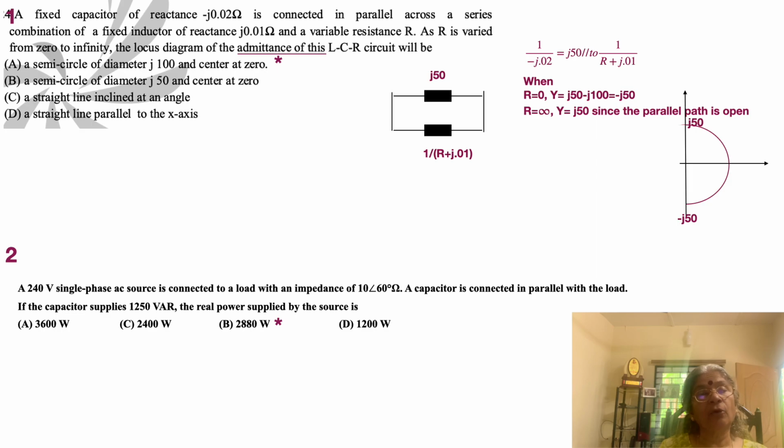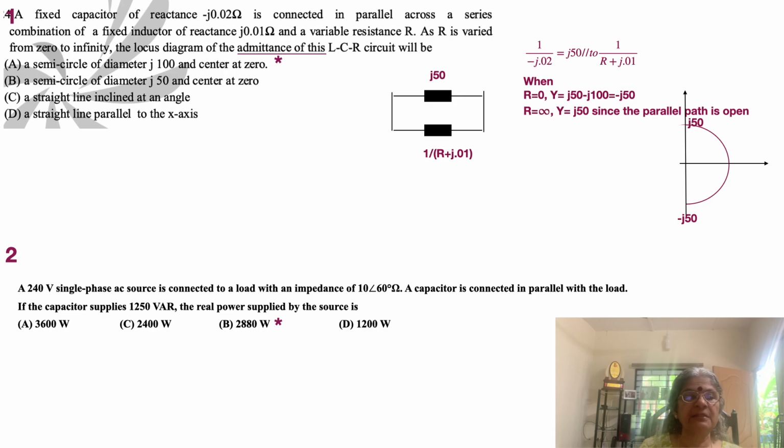But our requirement is only to find out the active power involved. So this is the distinction that we have to make. What's the active power involved? We have 240 volts. It is an RMS value, and it is line to neutral. Because it's single phase, 240 volts, and then there is an impedance of 10 ohms. So 240 divided by 10 is 24 amps, and then there is a power factor involved, which is cos 60. Put them all together, it is 2880. Only when we are going for three-phase circuits do we have to think about line to line. This is all RMS value, that's all.